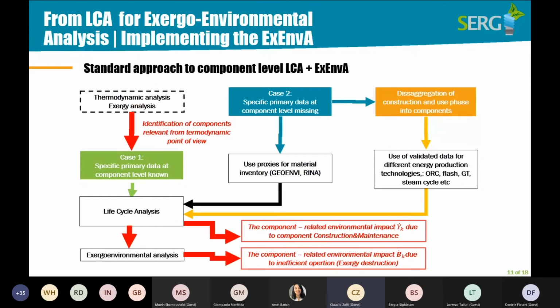First of all, we start from thermodynamic modeling and detailed Exergy analysis. So you must identify the relevant components from the thermodynamic point of view. Then we have two cases. The first one, when specific data are available at component level, we go directly to LCA modeling, calculating the component single score that represents the environmental cost and applying it to the cost balance.